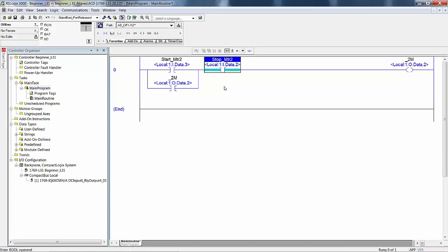But just to give it a more conventional look and match the manual, I'm going to go up here and I'm going to type in start conveyor 1 push button. And of course, there's no tag by that name. When I click away from it, we have an undefined tag. And I'm going to drag this over here to this tag Mimi, and I'm going to go in and change the ART to OP. Again, we have an undefined tag.